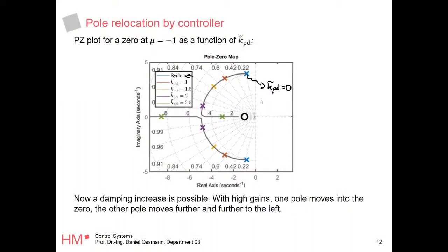But the root locus methodology always draws the lines only for the gain, and if you decide, I don't like that curve, I want to have it more to the left, then you add zeros or poles to your controller and draw the line again. And then you see what you can reach with this controller, right?